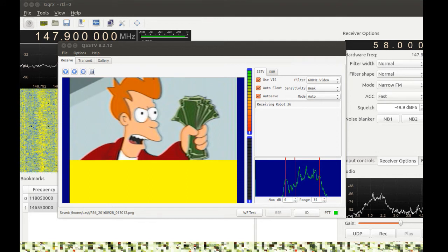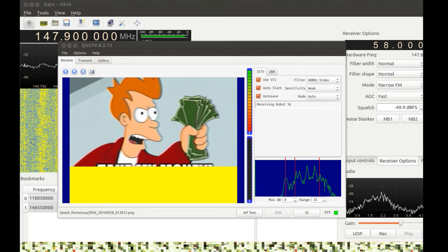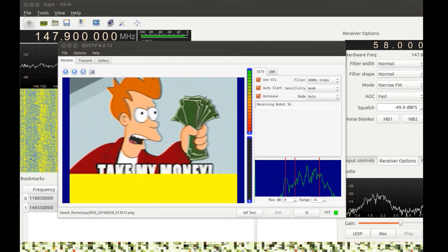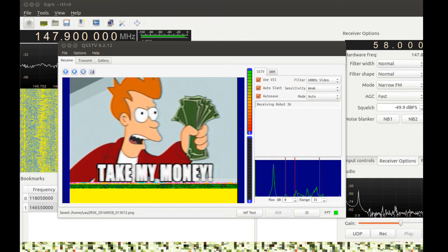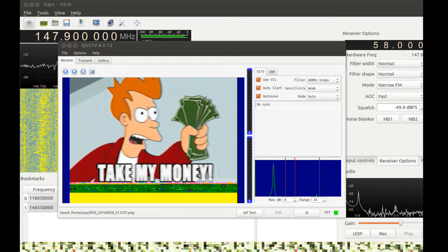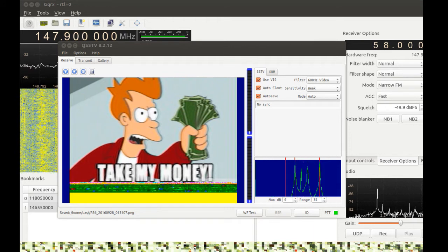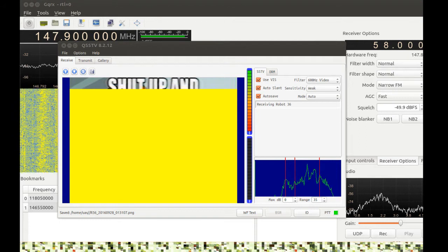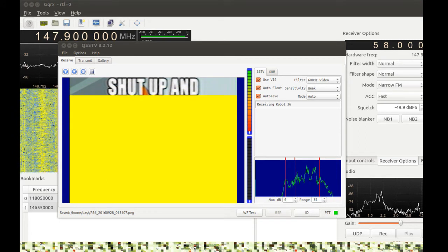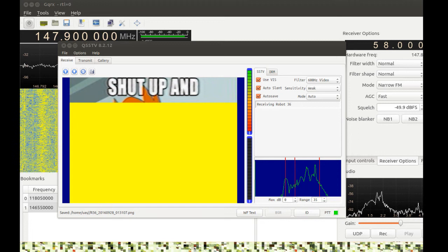Your FFT size is way too high. Drop that FFT size down to like 8192. It's got an i7 processor, so it's got some. Yeah, whenever anyone's having trouble, that's the very first troubleshooting step: take some of the load off the processor. Okay. Now put that back on frequency.